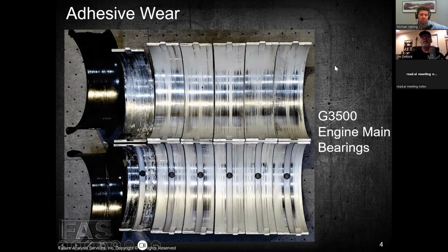So I guess I might as well go ahead and give you the root cause of this failure here. Since we talked about contamination a good bit last week and abrasive wear, it was actually what we would consider a dirty build, meaning that there were a lot of abrasive contaminants left in the suction screen. There were abrasive contaminants on the back side of these bearings, which is an indication that there was dirt present in the caps when the bearings were installed, which also reduces the oil clearance because we're pushing that bearing up a little higher.